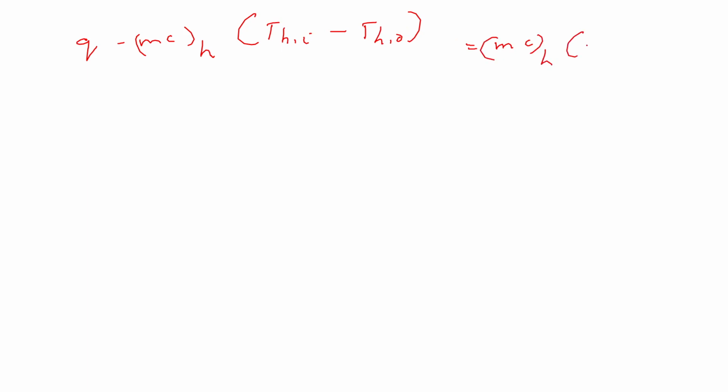We were taking three assumptions here. First, negligible heat loss to the surroundings, so we are neglecting surrounding heat loss, and kinetic energy and potential energy changes are also neglected. So first, from the overall heat energy balance, you have to calculate Q equal to m_h c_p,h (T_h,i minus T_h,o) equal to m_c c_p,c (T_c,o minus T_c,i).